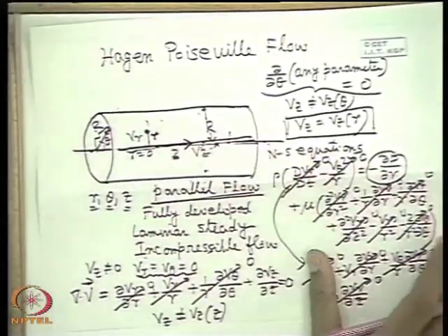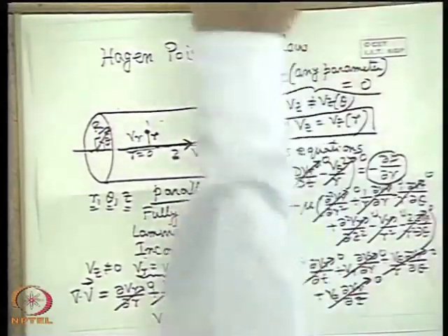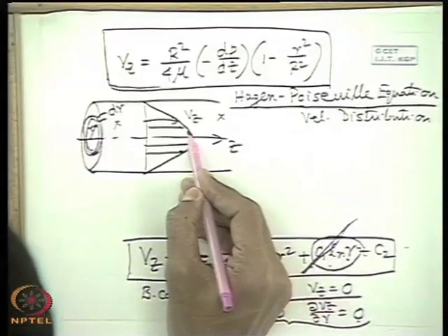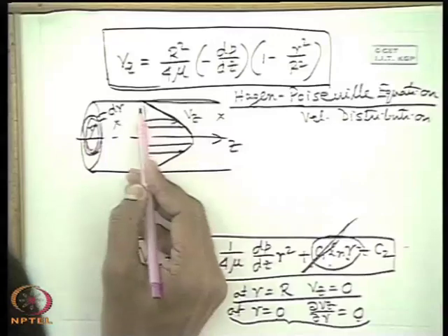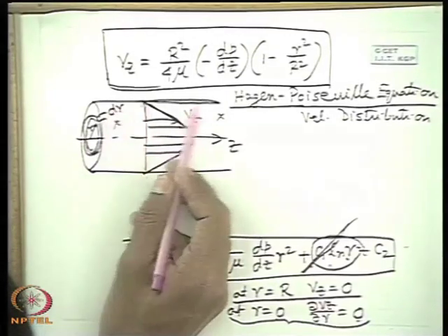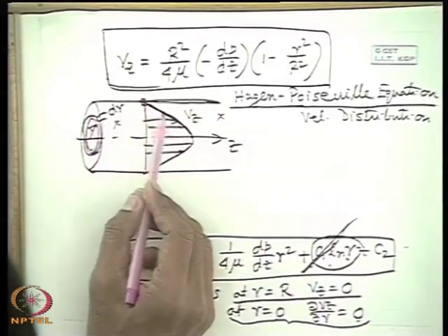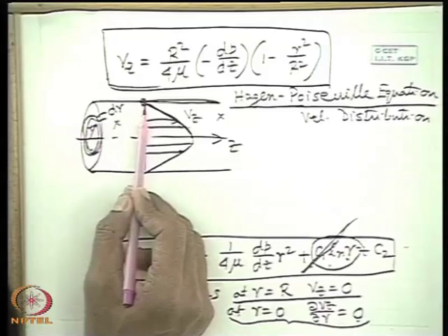If you see the velocity profile here, the velocity is decreasing with increasing r. That means r is not measured from the solid surface. At a solid surface at rest the velocity is always 0, that is the no slip condition. So velocity must increase from the solid surface, and normally the coordinate should be measured from the solid surface.